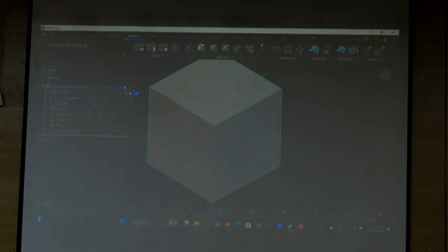The other type is 2D lattices. 2D lattice means the cross section is the same. And the other type is TPMS. The good thing about TPMS is that it is easily printable, and the properties are higher for TPMS structures. That is why, as a researcher, if you find any journals, mainly people are working on TPMS structures, because everyone knows that TPMS lattice structures have better properties than strut based. But it depends on the application also. If your application needs strut based lattices, then you need to work on strut based lattices.